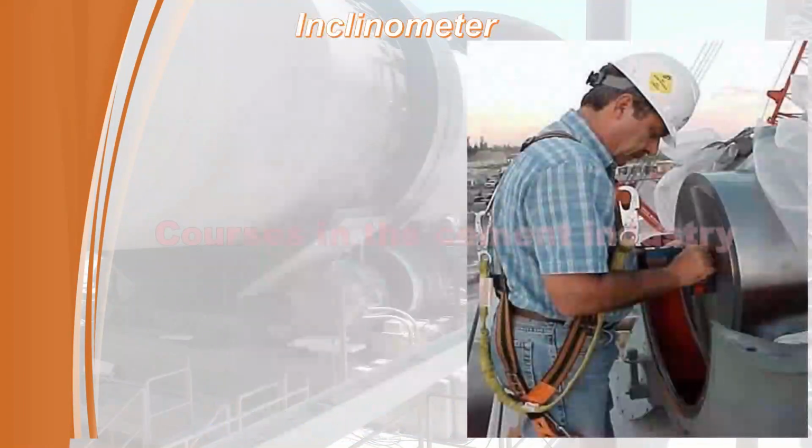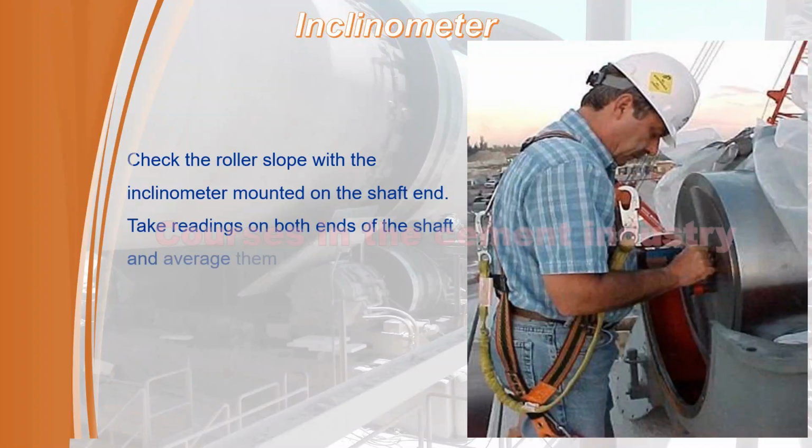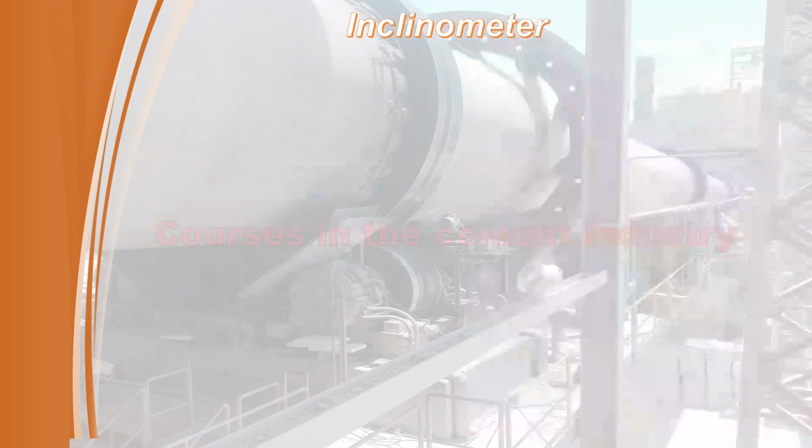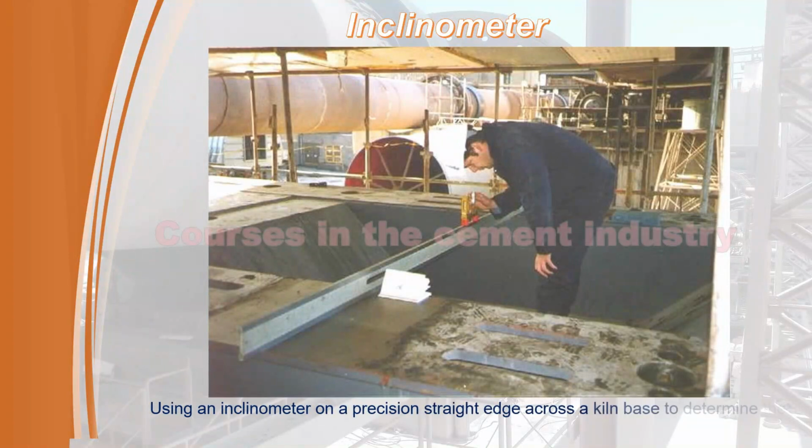See in the figure. Important note. Check the roller slope with the inclinometer mounted on the shaft end. Take readings on both ends of the shaft and average them to eliminate the effect of roller shaft deflection. See in the figure. Using an inclinometer on a precision straight edge across a kiln base to determine the correct slope.